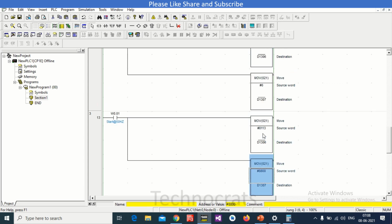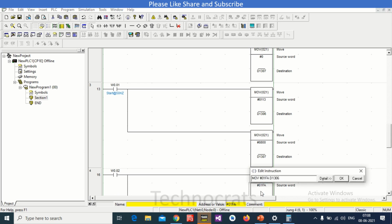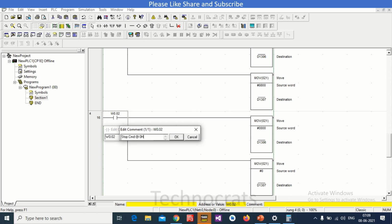And if you want to stop this drive and also reduce the frequency to 0, you can use W0.02. Okay, Ctrl V, and you can use 000, and again here 0. So this will give the stop command at 0 Hz. The frequency will also reduce to 0.